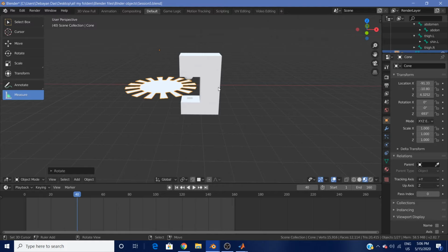counter. We'd be able to count the number of steps it took before the next interrupt was called, and by knowing the clock frequency, we'd calculate exactly how many seconds it took. And once we know how many seconds, we could calculate what the speed of the motor was. If this was connected to a wheel or something, we could know how much distance the robot moved by using these encoders and figuring out how much the wheel has actually turned.